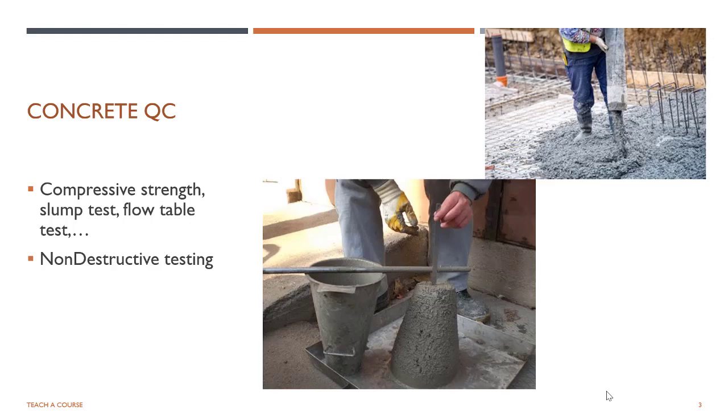The first important subject is concrete quality control, because we have the material itself that we need to control. What about the construction process, the boring, as you can see in the photo of the boring? How can you make quality control through all the processes of the concrete structures, and how can you control it according to the checkpoints? The checkpoint will be through the test, the compression test for the cube or the cylinder. What about the steps? It follows a standard.